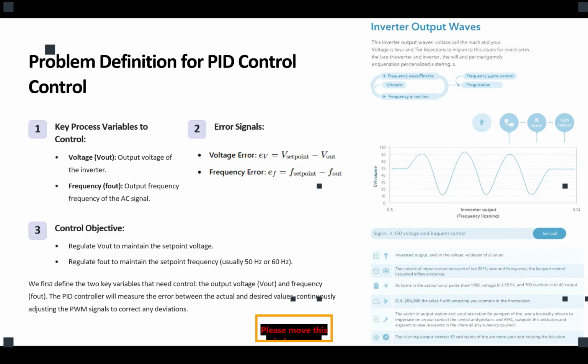Okay, so that being said, basically all control variables shrink to two variables. We have to control our voltage for active and reactive power. And for the PLL, for the synchronization, we have to control our frequency. So in inverter-based resources, we have two main variables to control in our control system. Are we good so far?